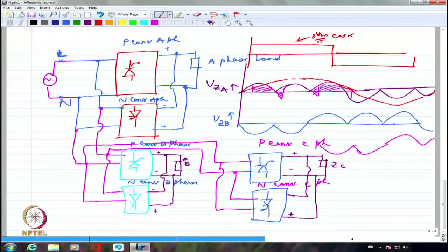Most of the times, synchronous machines may be run at slow speeds. For some kind of cement mill where you are trying to grind limestone and so on, all those things work very slowly. It is inching. Most of the motor drives will be inching slowly. So in those cases, these can come in handy. From 50 hertz, you may come down to 10 hertz or 5 hertz. So in those cases, cycloconverters come in handy.